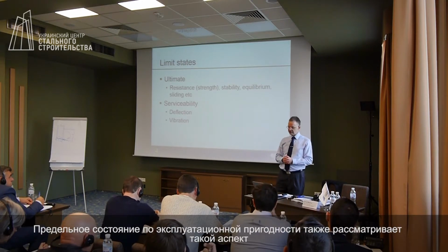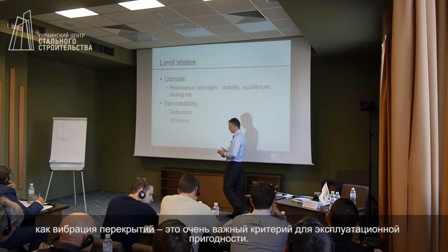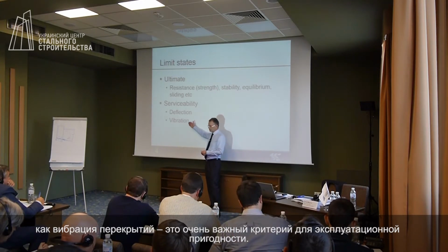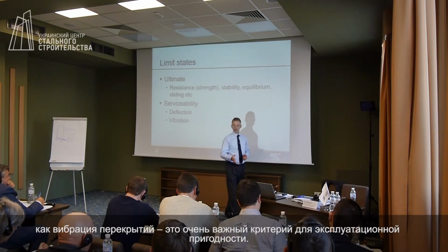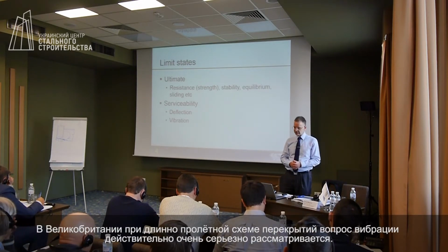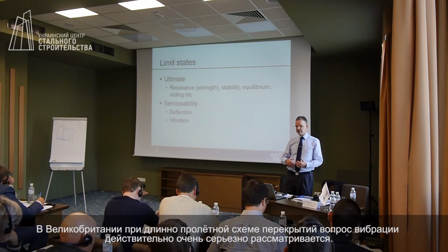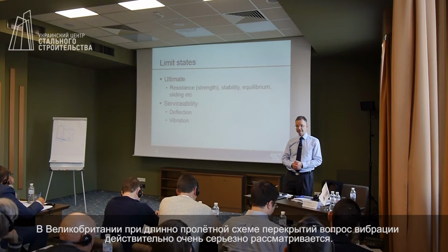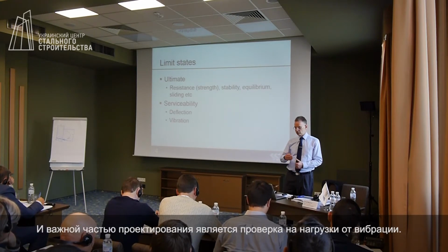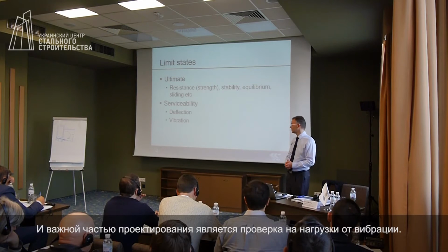But serviceability also includes a number of things. Floor vibration would be a really important serviceability issue. So with lightweight floors in the UK, with long span floors in the UK, there is concern about vibration. And to verify that the beam is satisfactory in vibration will be an important part of the design process.